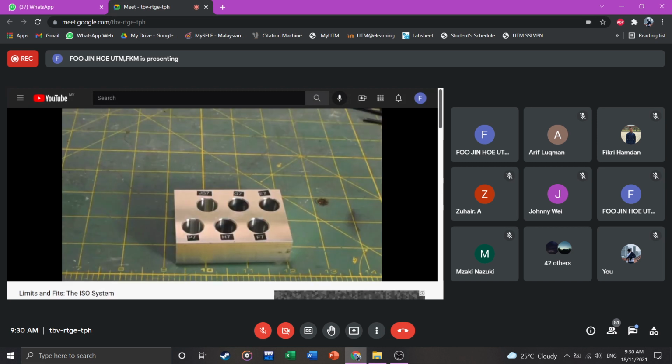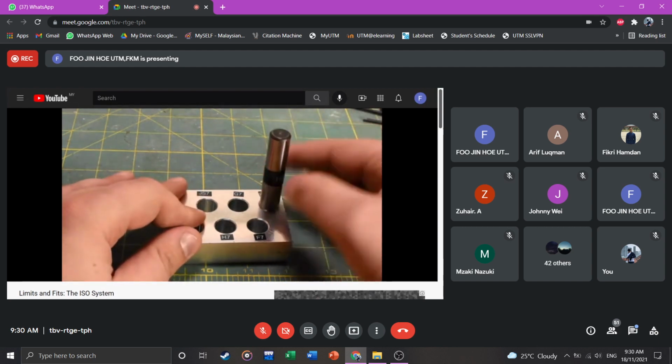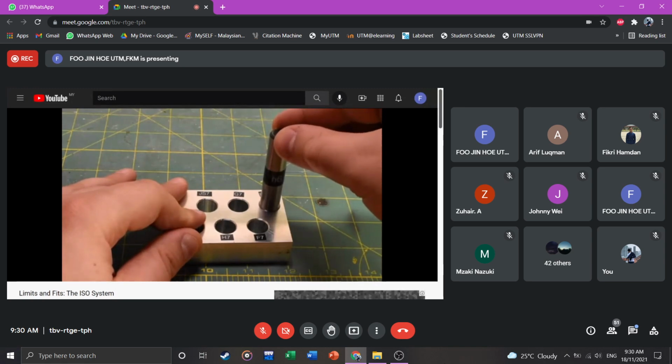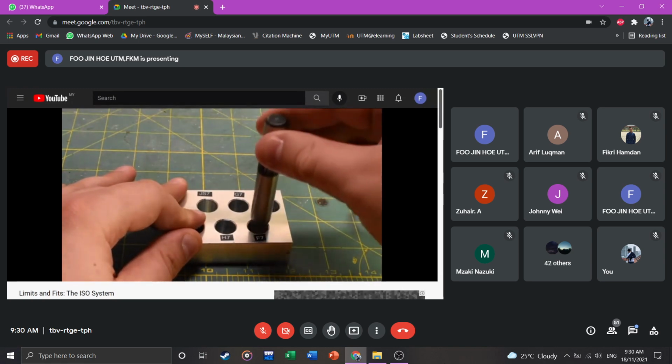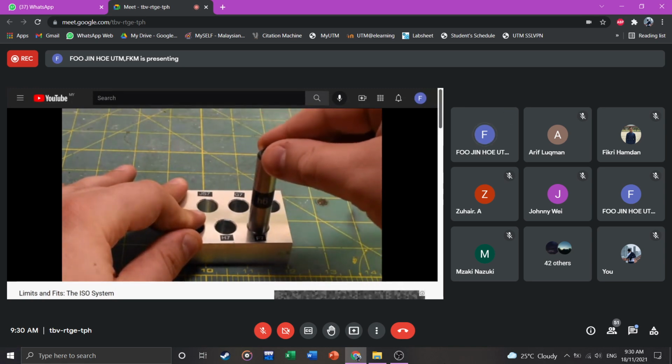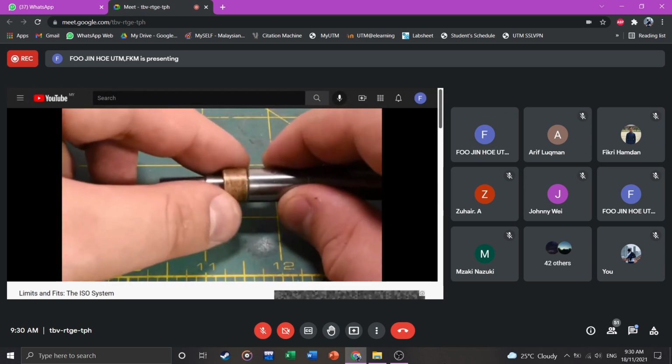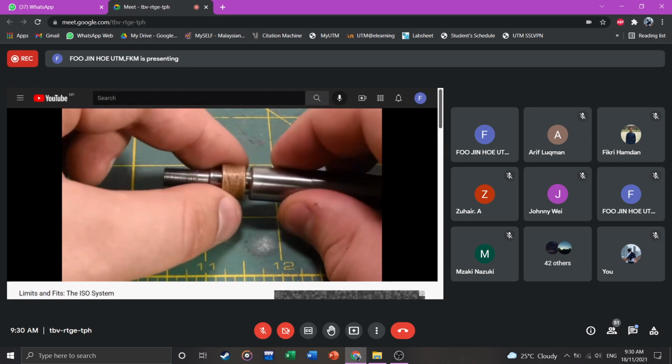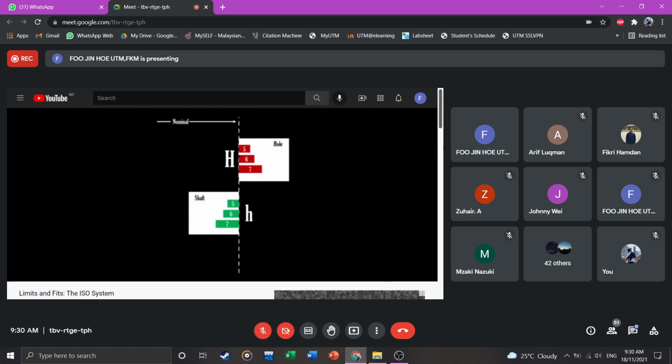Okay, so now we have a naming scheme for tolerance zones. For a given fit, we will usually have one component driving the other one's required tolerance zone. In this example, where we bought the dowel pins, we have no input on their tolerance, so it was a shaft basis fit. If we're designing a shaft that has to fit in the purchased bushing, we can't control the tolerance of the bushing, so we have a hole basis fit. Shaft or hole basis fits often use an H tolerance zone, respectively, since the H tolerance zone contains the nominal size as one of the limits.